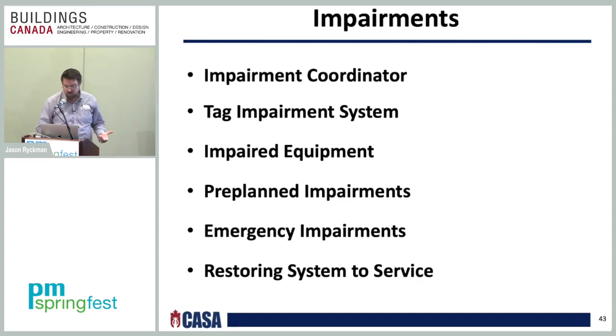So a formal impairment program establishes procedures for maintaining the system control valves in the correct position. Furthermore, implementation of an organized impairment program can also minimize the length of time that a system is out of service. Chapter 15 provides the basic requirements for such an impairment program. The success of any impairment program is determined by the support it receives from those responsible for implementing it.